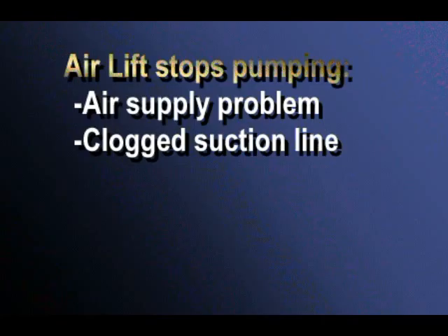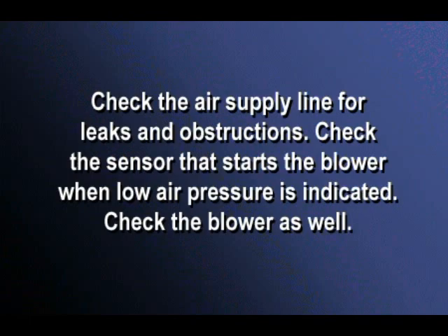If the airlift pump has just about stopped pumping, expect a problem with the air supply or clogged suction line. Check the air supply line for leaks or obstructions. Check the sensor that starts the blower when low air pressure is indicated. Check the blower as well.